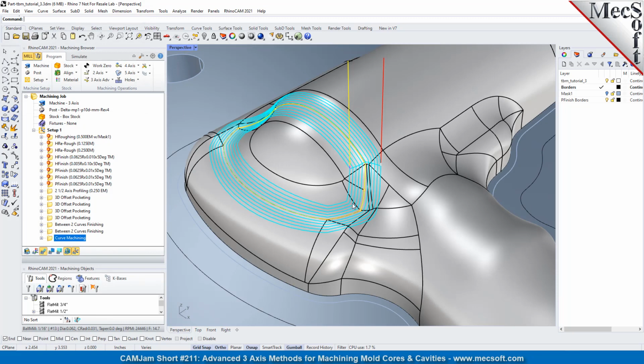Okay, so you've got a three-dimensional toolpath that's following the selected curves that we created, and it steps over 20 thousandths, and there's a total bandwidth of 0.1 on either side. So you can use this to do touch-ups in certain areas of the part, and all you need is a curve.